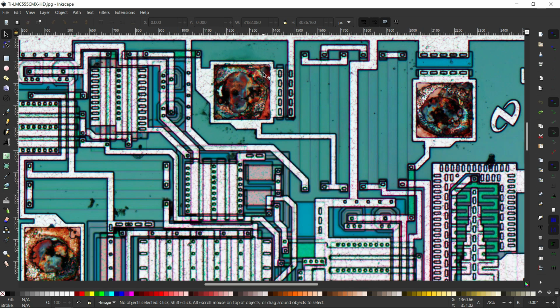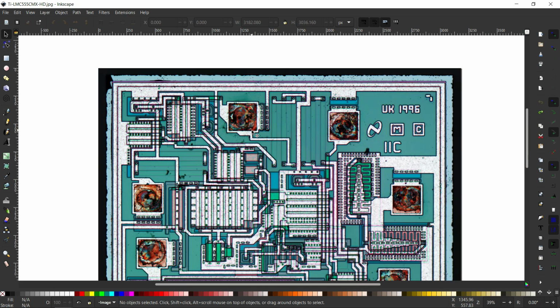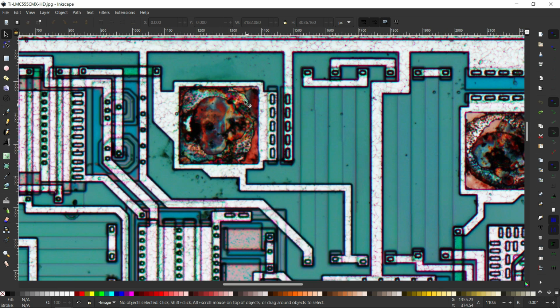So whatever you are seeing here, the larger square pads, these are all pads. Because in the older technology they don't have a bump pad, usually they will create a wire pad only. So wire bonding only they will use, because this IC555 is a dual in-line package. Dual in-line package is a kind of packaging technique of the IC. See, next to this pad they have a diode connected structure. See this one. This is acting as an ESD diode.